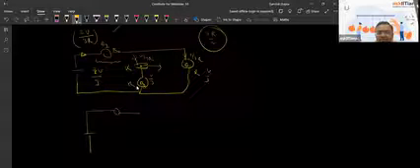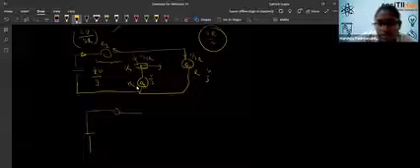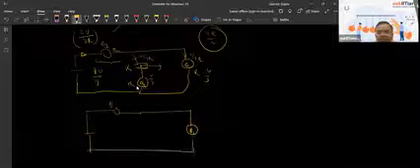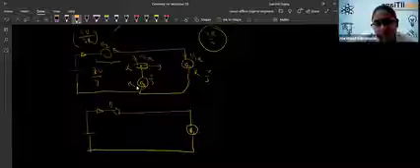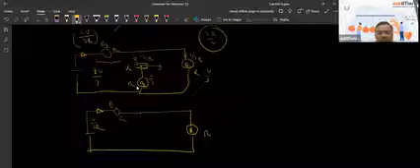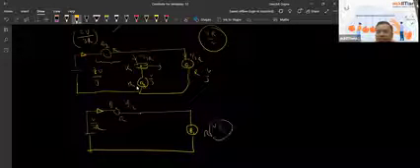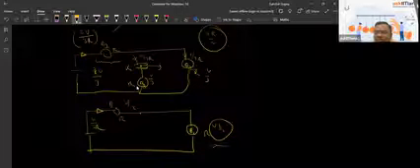And when the switch key is open, the circuit is like this. B3 will not glow. So this is B1 and this is B2. Here V by 2R current will flow, because R and R, the effective resistance is 2R. And what is the voltage across this? B1 drop is I into R, V by 2 and V by 2. So see, across B2, the voltage has increased.